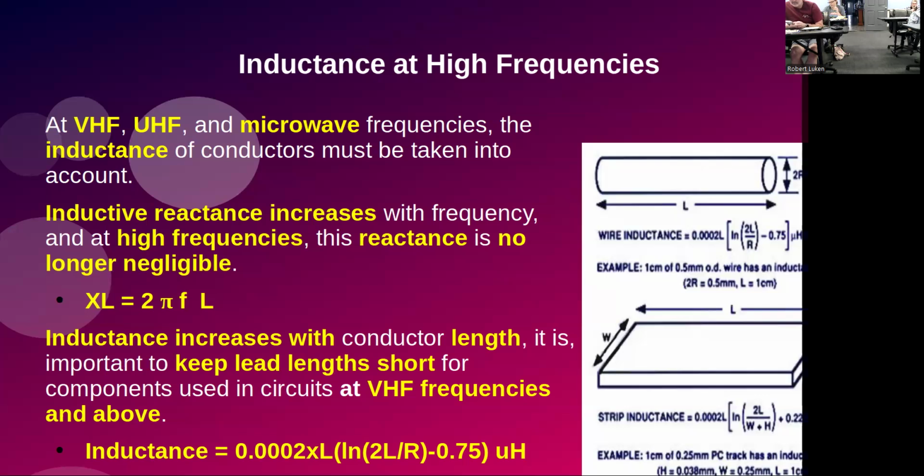So when you're doing very high frequency work, one of the things you have to look out for is the actual wiring and the lengths of connectors. It gets to the point where for certain things, you have to make sure that the path lengths are exactly equal, so you don't have a phase shift between them.